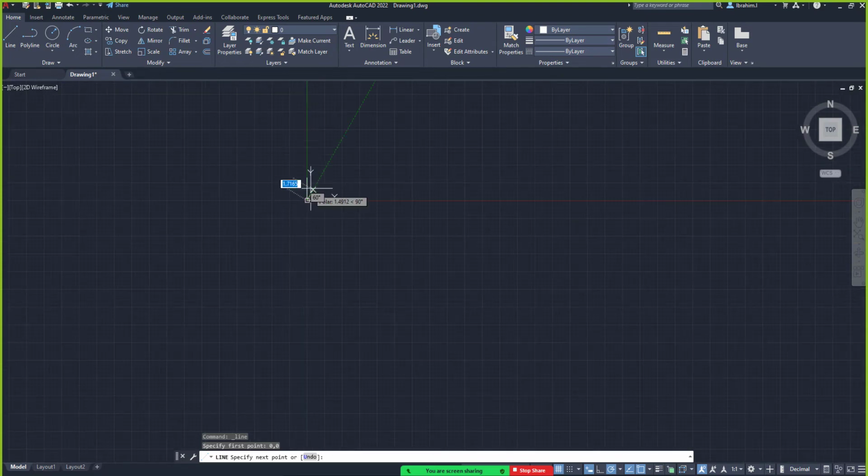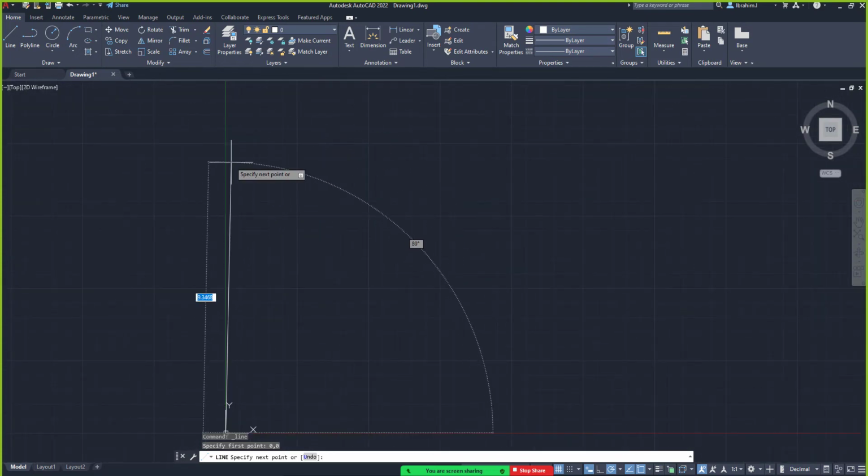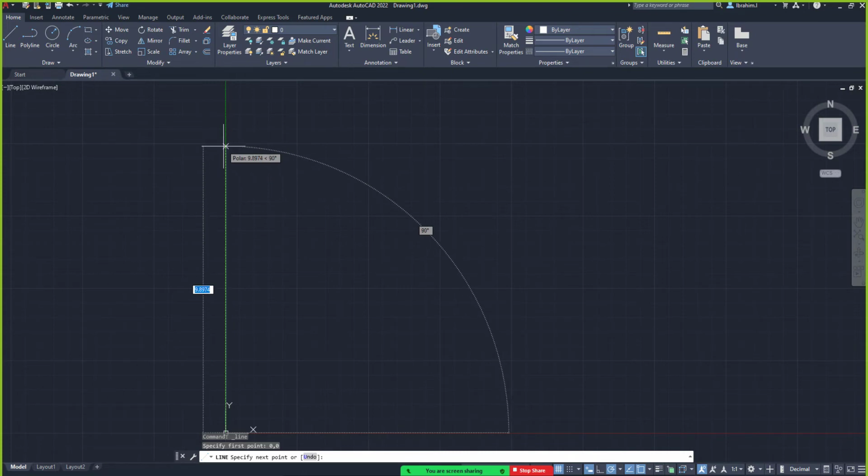And then from there, if I decide that I want to draw a line, what's the length of the line I'm trying to create? Let me create a line of 10 mm. And then I'm going to click on tab. When I click on tab on my keyboard, can you see what is happening? The first section is where I was able to enter the length of the line. When I click on tab, it jumps to the angle at which I want to draw the line. Are you with me?